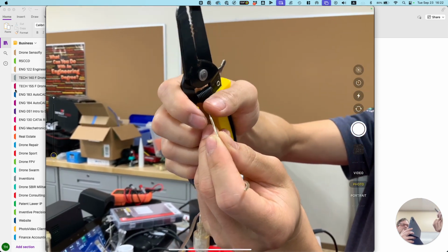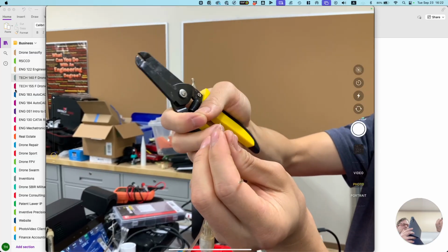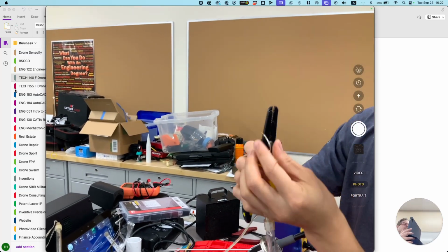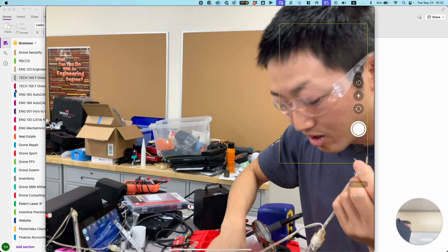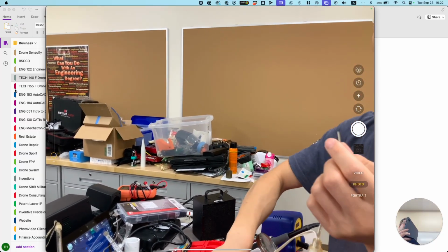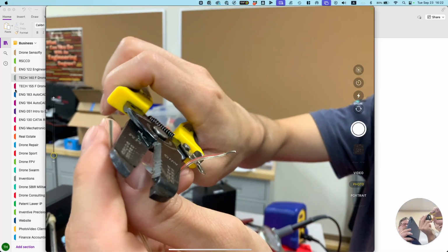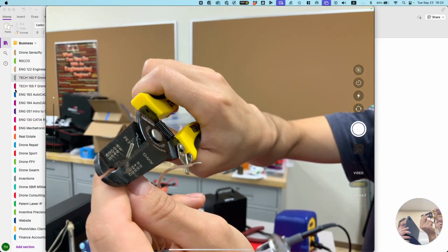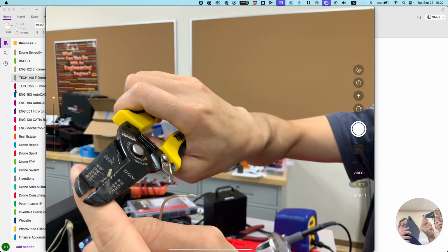Okay, there I go. I have the full amount of cable there. You can also look at the piece that just cut off, and if you see strands in there, you cut too much. You cut too deep. Okay, so same thing once again.